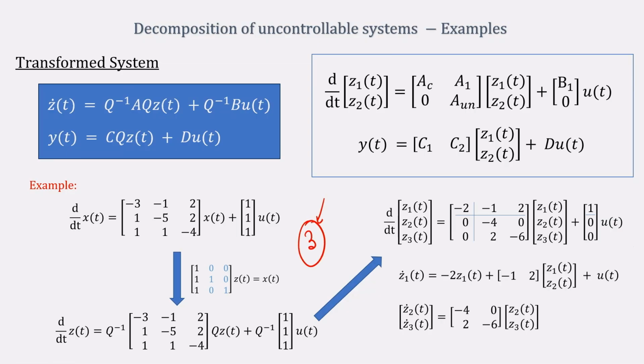What do I mean by state space dimension? The state vectors are still of dimension 3 cross 1. In this transformed state variable, I can only change the top part, the first element, from anywhere to anywhere in a finite time, and the bottom part, which is a 2 cross 1 matrix, I won't be able to change as I wish. That is the uncontrollable state variables.